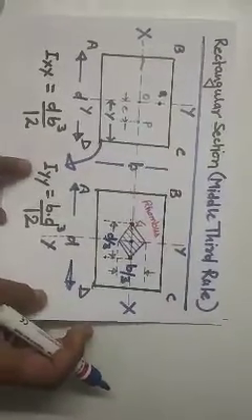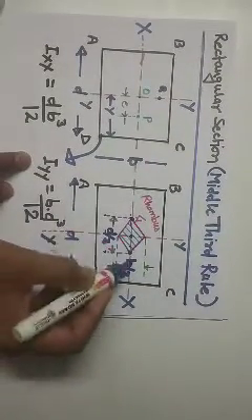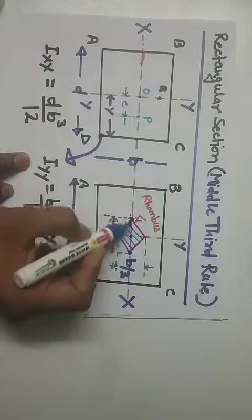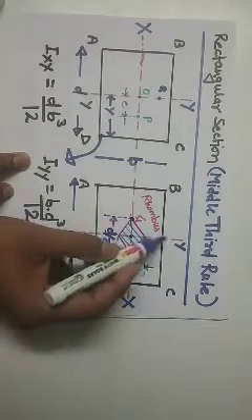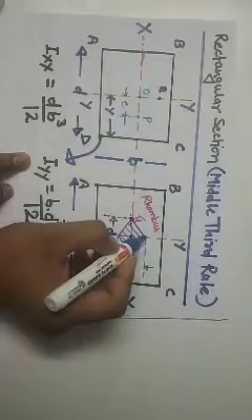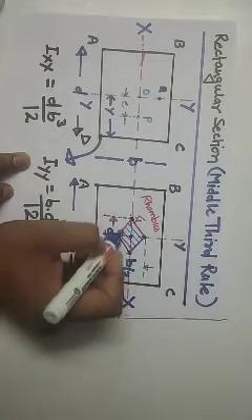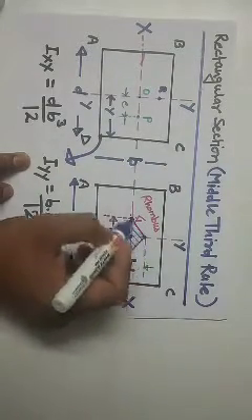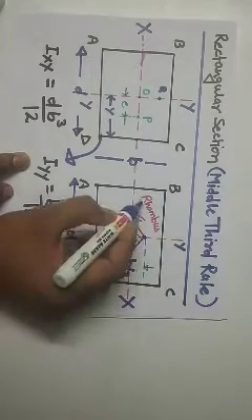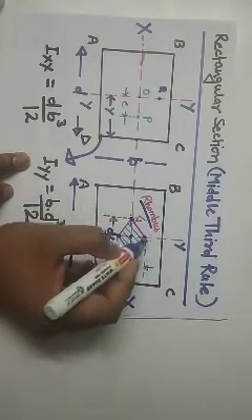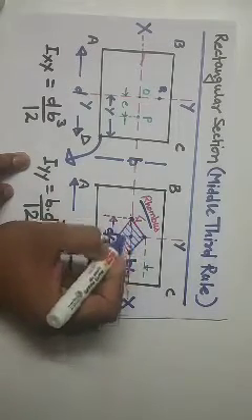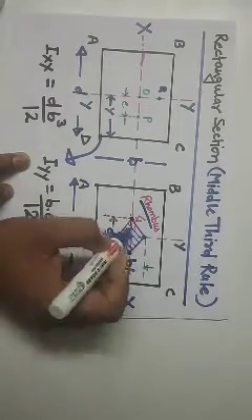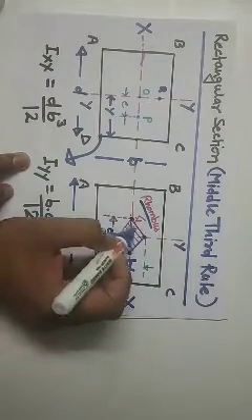So we have found 4 points. When load is placed on the x-axis, 2 points are found, and when load is placed on the y-axis, these 2 points are found. When we join them with straight lines, a rhombus will be formed. This closed area is also known as the kernel.